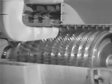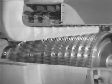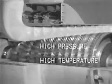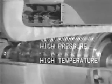Now, with an increase in pressure goes a similar increase in temperature. So the air leaving the compressor has gained high pressure and a high temperature. This is done by alternately speeding up and slowing down the air in an ever-decreasing volume of air path.